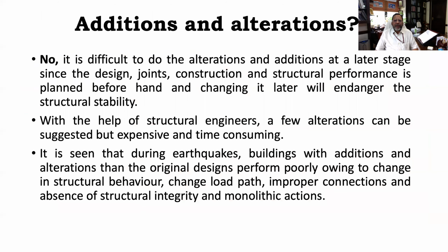Addition and alteration is very difficult here because it's a shear wall construction of your structure. It's a pure RCC construction, so it is very difficult to break this RCC at a later stage. And if at all you want to add a new block to this, you have to properly connect the old structure with the new through reinforcement.